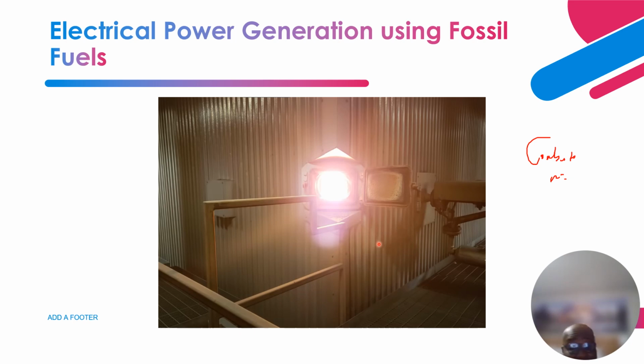Sometimes you can even have 30 burners. The pulverized coal goes through the burners, is ignited and burns, so the heat is transferred into the water that flows through tubes in the peripheral walls, and that heat creates steam.